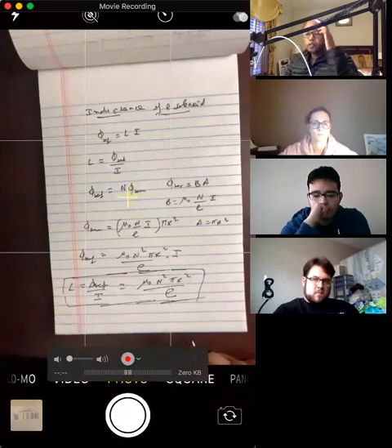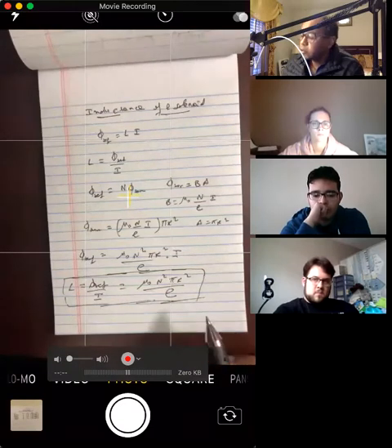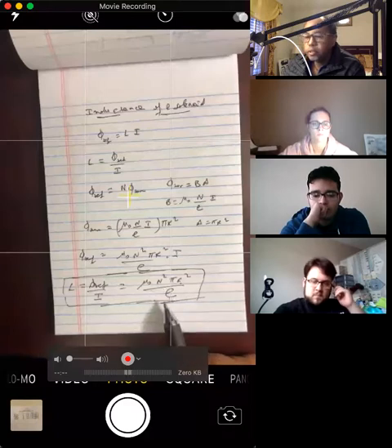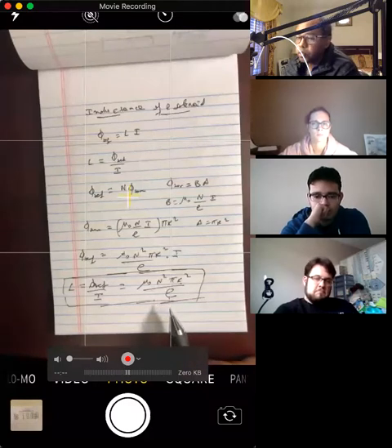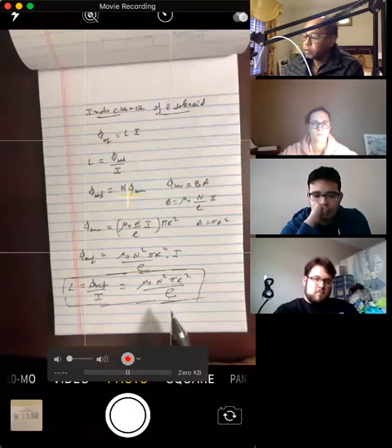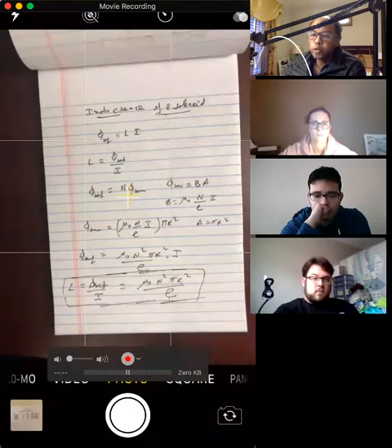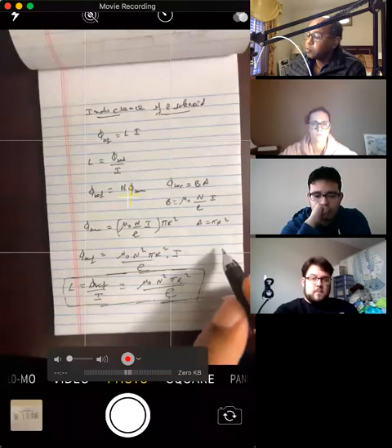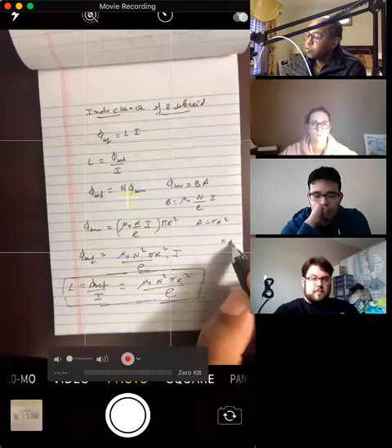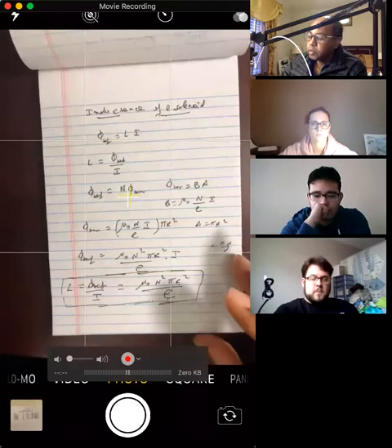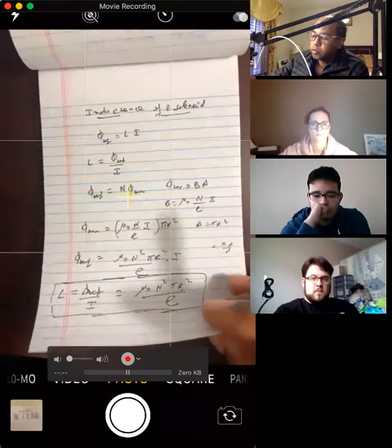Okay, so you see it depends only on the geometry of the coil. You've got the radius over here, you've got the length of the solenoid, the number of turns. That's it. It depends only on the geometry of the coil. So it is a constant. All right. So this gives you the inductance of the coil. You remember for a capacitor, we have a similar expression. If you've got a parallel plate capacitor, for example, we have this formula for the capacitance. It's simply a function of the geometry. In this case also, the inductance depends only on the geometry of the coil.